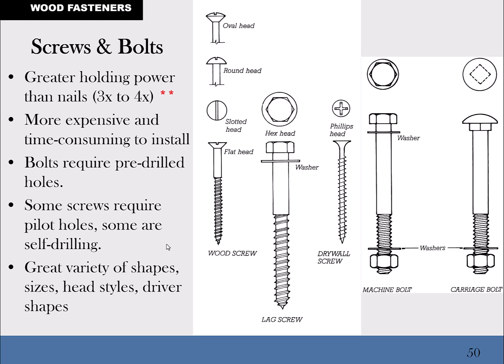The carriage bolt, it's going to kind of sink in on purpose and leave the head so that you can't grab a hold of it, but it's likely to be held by the wood as it squishes inside. So washers are an important thing, and make sure you have the right size and thickness of washer for what you're trying to do. But they give you tremendous fastening ability here. So screws, and now bolts even more than screws. It's because the bolts are compressing two pieces together, particularly if you can get a good, strong, heavy washer on each end before you bolt it together.